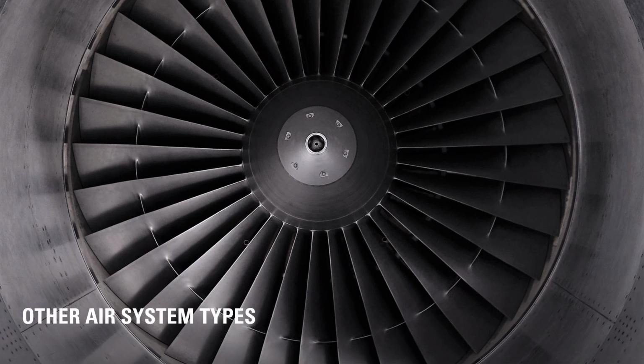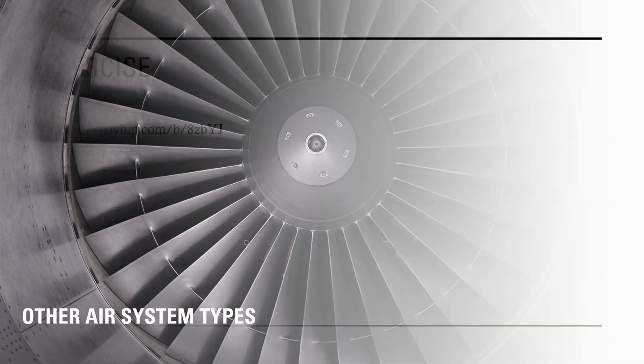That concludes the theoretical portion of Module 9, Introducing Systems. We've explored the logic behind how MEP systems operate inside Revit, the importance of connectors, the role of the system browser, and how filters improve clarity and coordination. Next, we'll walk through the full hands-on exercise and create a complete mechanical supply air system step by step.